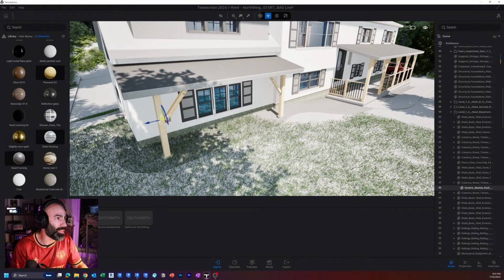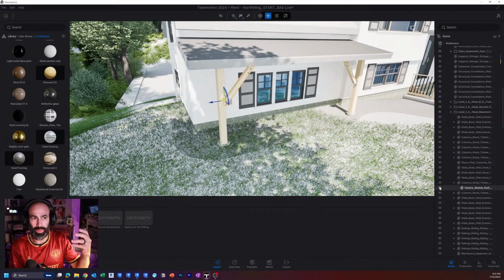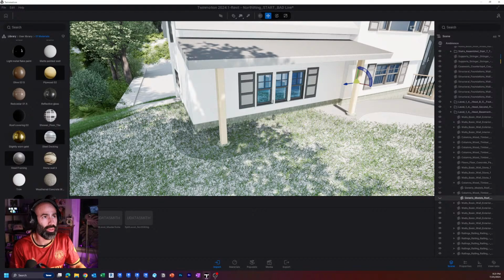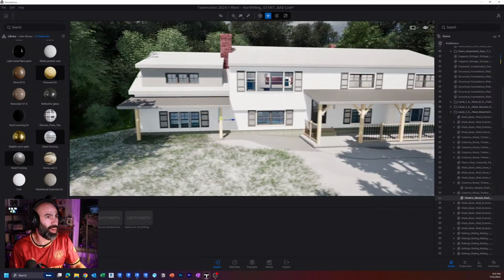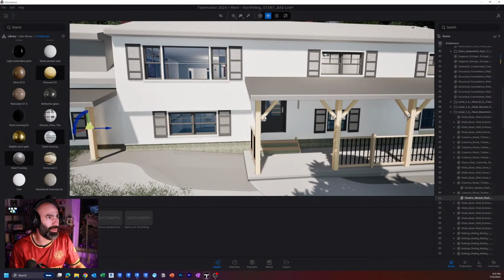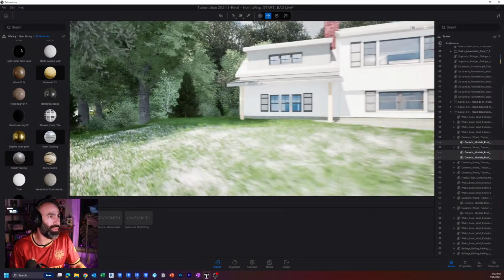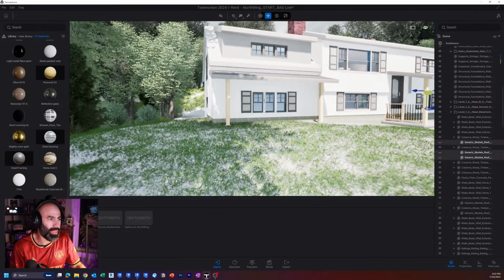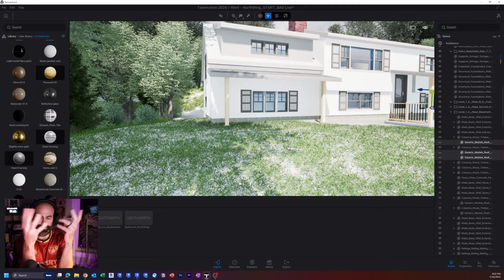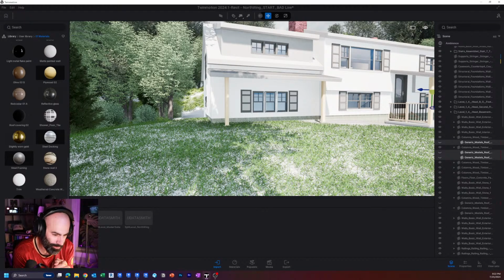And so I don't do a ton of moving, but what I might do is, for example, as I mentioned before, maybe I want to just do a rendering where these two columns are off, or these braces are off. So I'm selecting the braces and I'm turning them off. Without actually modifying the model, I can quickly make tweaks for the visualization and not have to go back. That's kind of cool. It gives you that flexibility. If it was combined by material, then all of those wood beams would all be combined because they were using the same Revit material.